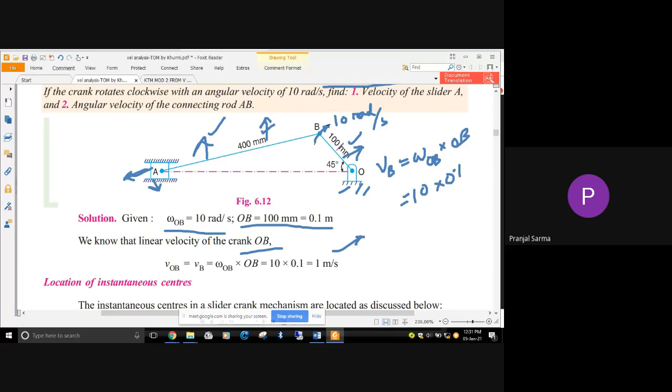The crank has got rotational motion. These are the hinge joints. Similarly, this slider, what kind of motion does it have with respect to this particular frame? It has sliding or reciprocating motion. Yes, correct. So it slides or reciprocates along the line of stroke direction. This is the line of stroke direction.